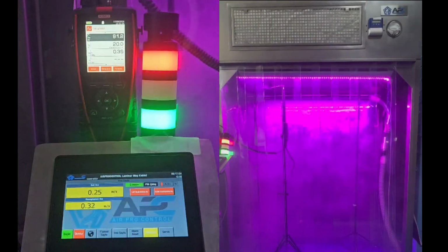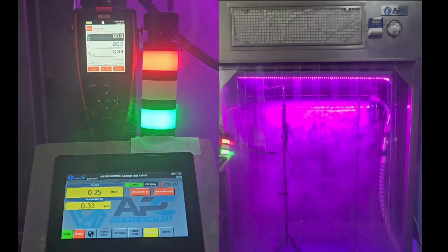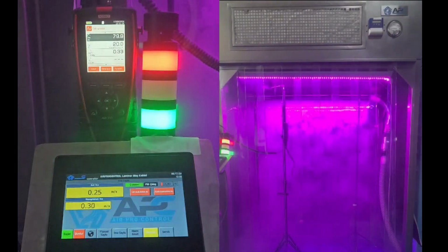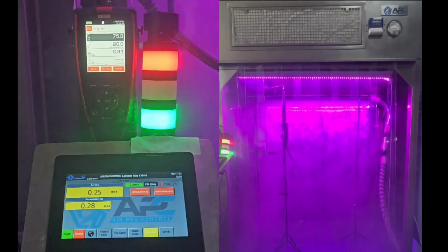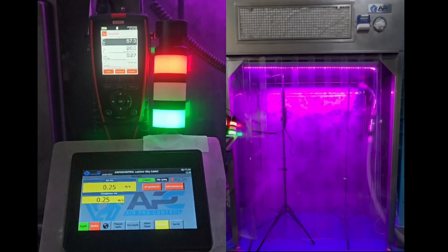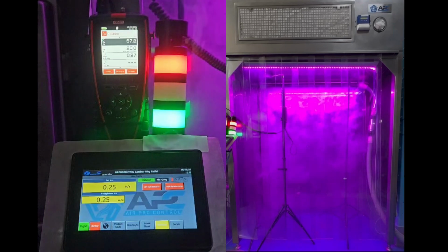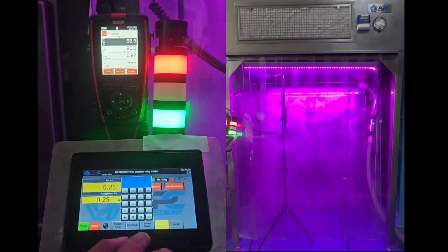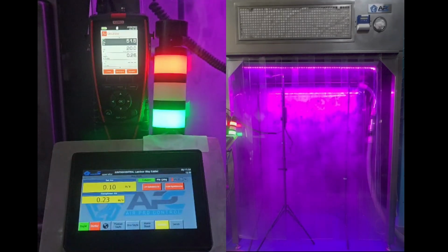Low air velocity in laminar flow can lead to several significant issues. It slows down particle transport, making it more difficult for clean air to carry particles away, which increases the risk of contamination. Additionally, reduced airflow can destabilize laminar conditions, resulting in turbulence that causes uncontrolled particle movement and deposition in